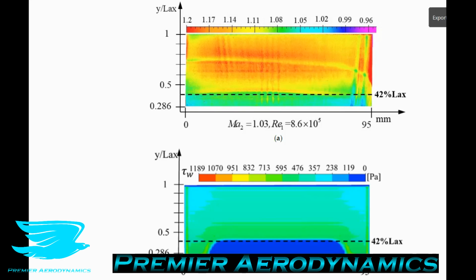So we can see that for 9b, the point at which the boundary layer transitions is at 42% of the chord downstream, and it's very clear. We go from a very dark blue point to an aqua point very sharply. In figure 9a, we also get a very sharp change. We go from a blue-green to an orange-red very sharply. Again, there is some variation, but that's due to the application of the paint, which is to be expected.